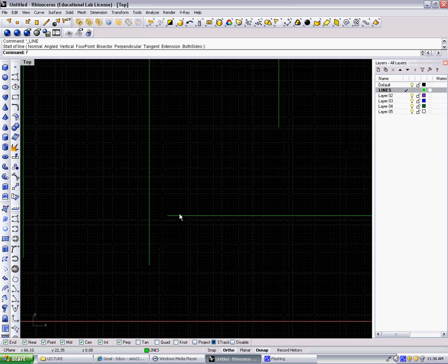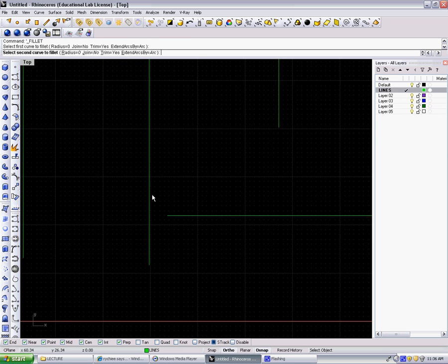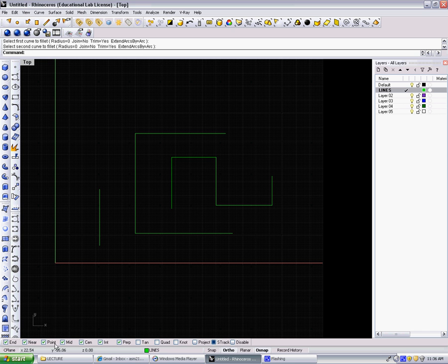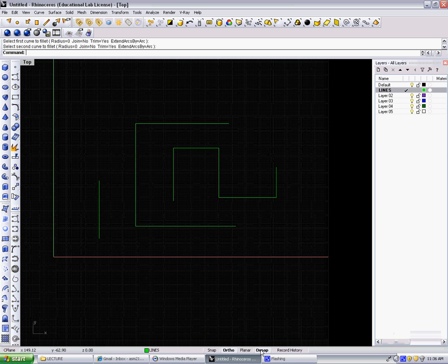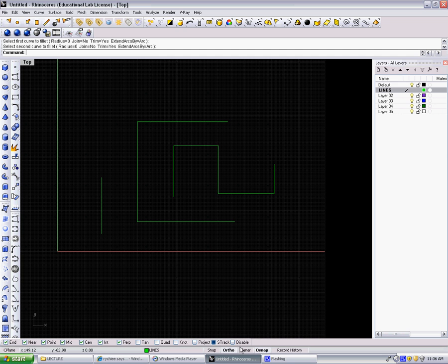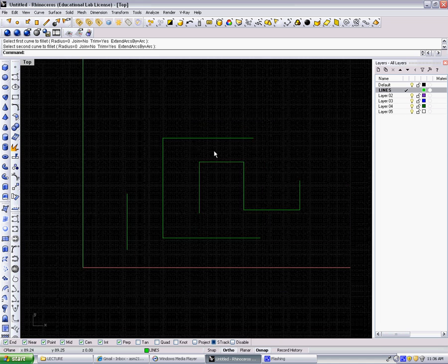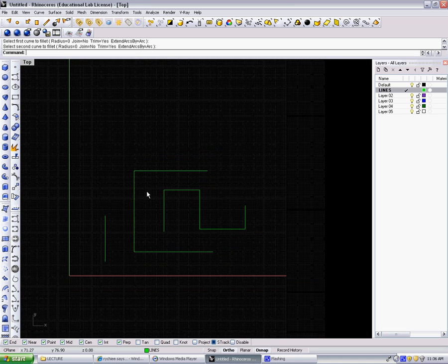You also have snaps down here at the object snaps. If you click on O snap, it turns them on and off. You can then also select the specific object snaps that you want to use. You can disable them if you're wanting to freehand draw for a specific moment. And then snaps make Rhino a very precise and easy way to use it, because they're really similar to the way CAD uses snaps. The third way to find tools in Rhino is just from drop-down menus.